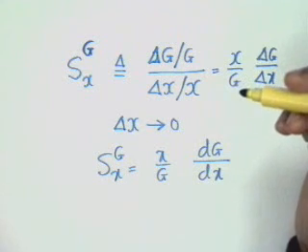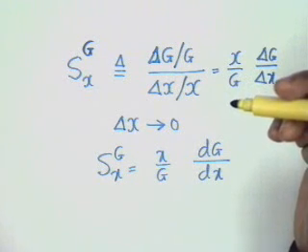In practice, for example, if you want to find the change of gain with respect to beta by device replacement, you know beta from one device to another can change by as much as 100%. So if you take two transistors, in one of them beta is 100 and in the other it is 200, obviously delta beta cannot be considered infinitesimal. So this definition will fail when delta x is not infinitesimal, but nevertheless we use this as a convenient measure. Shouldn't this be a partial derivative?